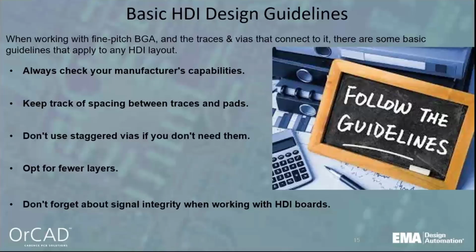One thing that's major, and I stress this to everybody, is don't forget about signal integrity when working with HDI boards. Any HDI layout that you're going to design, with high frequency guidelines, even RF, you're going to want to be able to use signal integrity and set the rules up for that. So it's very important that you're, first of all, dealing with your manufacturer. One of the utmost, I can't stress that enough, is having a constraint manager that's going to be able to handle the constraints so that you can implement those constraints into your design tool, and then the DRC can follow those constraints. And then the third thing is signal integrity.